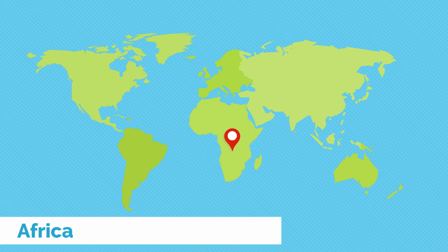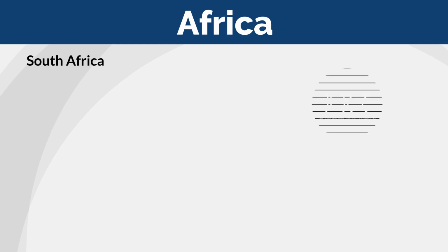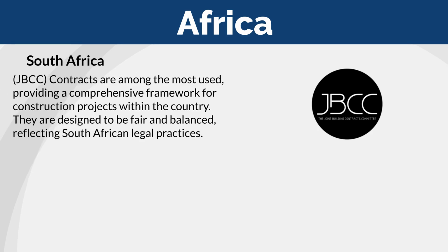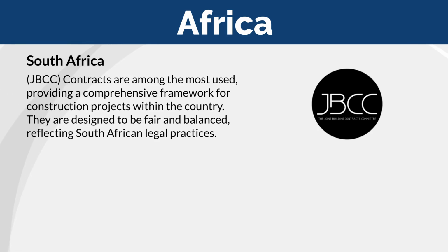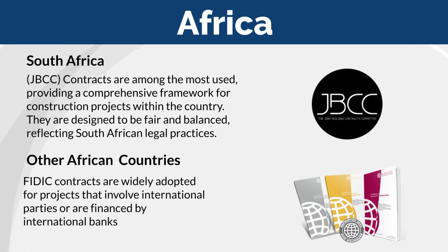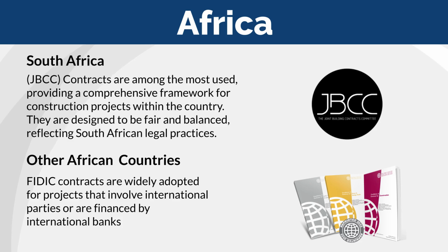Africa. In South Africa, the Joint Building Contracts Committee, or JBCC contracts, are amongst the most used, providing a comprehensive framework for construction projects within the country. They are designed to be fair and balanced, reflecting South African legal practices. In other African countries, FIDIC contracts are widely adopted for projects that involve international parties or are financed by international banks. The FIDIC suite is favoured for its international recognition and the clear framework it provides for managing complex projects.